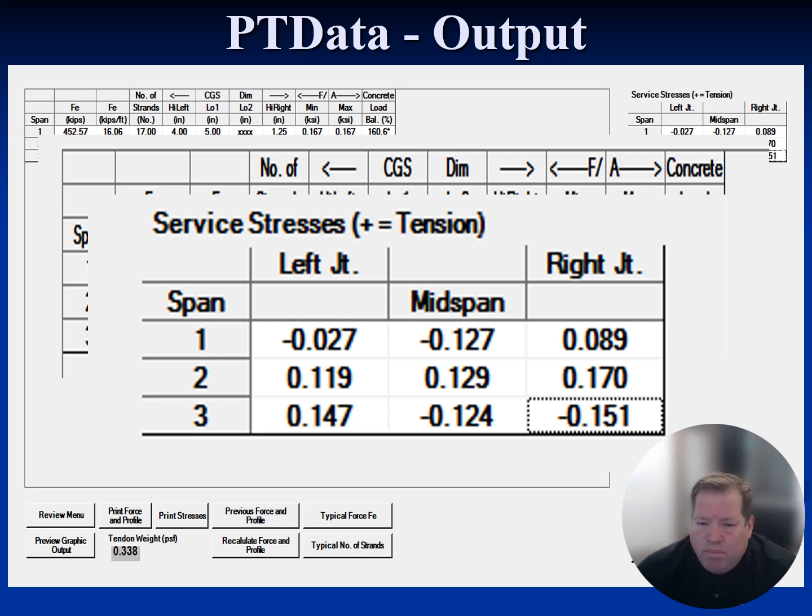The thing about balance loads is there really is no stress check for balance loads. If you have 400% over balance, you're typically not going to get a flag that says this is not a good idea. We're at 161%, which is obviously a lot higher than 100. But if you just look solely at stresses, there's no code violation. So again, there's no code section for balance loads, but it typically is a very good indicator of a design that is going to work well and minimize the chances for overbalancing and blowouts.